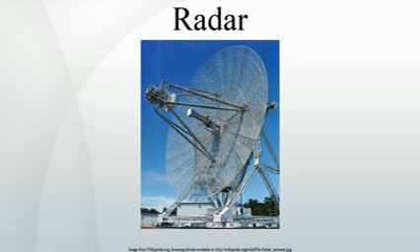The most effective clutter reduction technique is pulse Doppler radar. Doppler separates clutter from aircraft and spacecraft using a frequency spectrum, so individual signals can be separated from multiple reflectors located in the same volume using velocity differences. This requires a coherent transmitter.